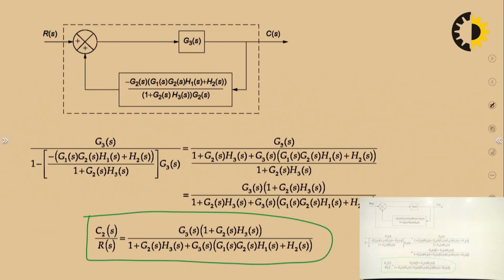So this is the overall transfer function which we have calculated after solving this: G upon 1 minus GH, because positive feedback is there. So this is G, and this is 1 minus, if it is H, G into H. Like this you can solve it.